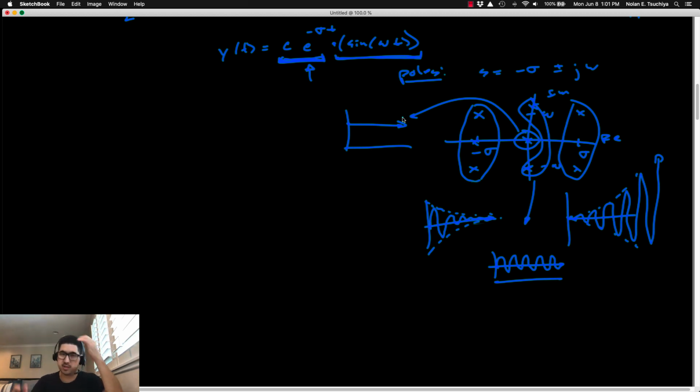Putting all this together, what it's looking like now is if the poles are to the left of the imaginary axis, the system is stable. If the poles are to the right of the imaginary axis, the system is unstable. If your poles are anywhere on the imaginary axis, the system is marginally stable. Right? That would be a very clean, concise definition of stability as it pertains to the poles, but unfortunately we can't draw that conclusion necessarily.